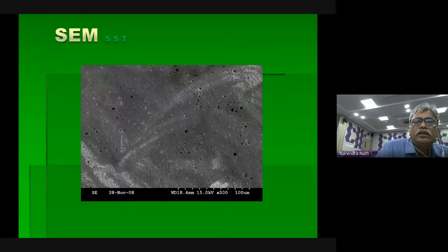And this is solid solution treated. So here also, if you look like this, you can see grains. But unfortunately, we are using HF, and any small amount of HF is very dangerous, because suddenly it will burn the surface. We tried for different times, from microseconds up to 30-40 seconds. We miserably failed, but the optical image is coming very nicely.